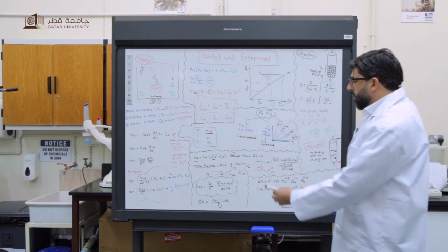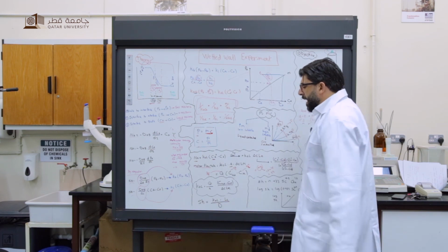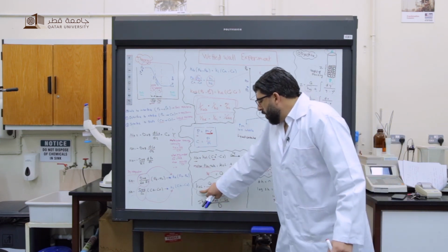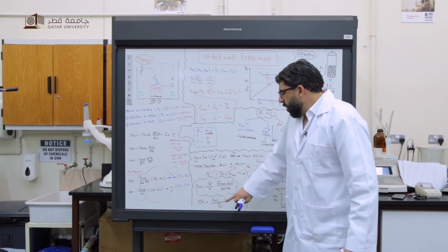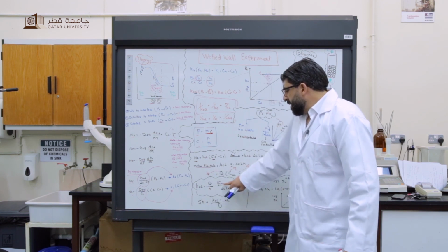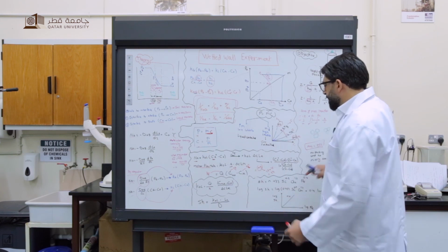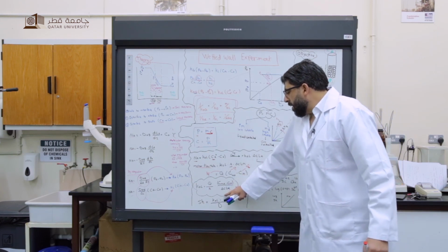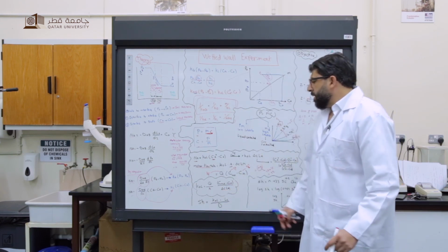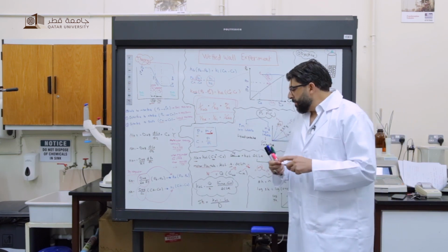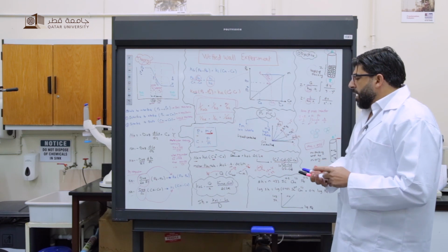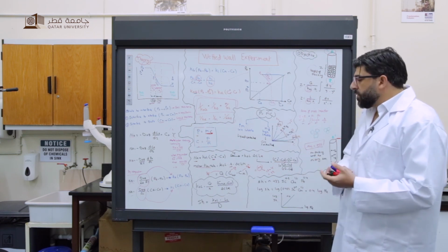Then by equating both equations, we can find K_OL, the overall mass transfer coefficient, equal to Q over area times (C_out minus C_in) over the overall ΔC_LM. So by this we can find the overall mass transfer coefficient experimentally. Also we can find the Sherwood number.